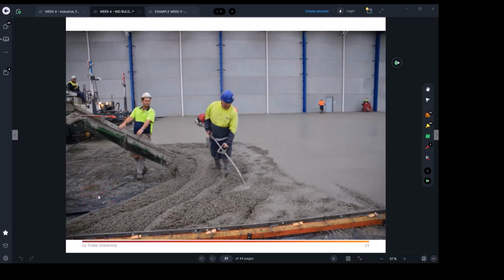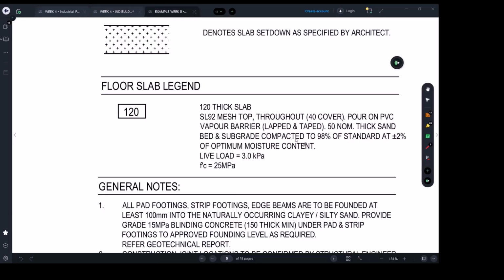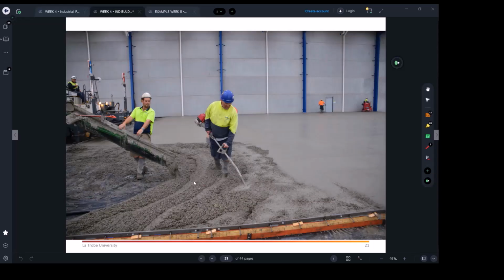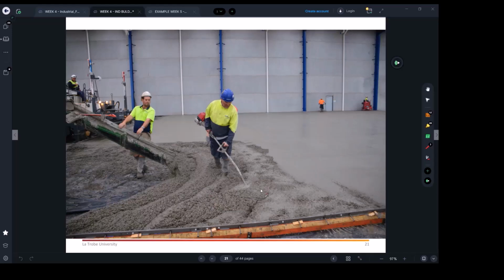Usually below the black sheet, you have the prepared subgrade. And yes, it needs to be checked as per the tables and specification we discussed. That's one thing. And then the subgrade needs to be compacted to these limitations, which would have its own contractors to do, and you're going to be given a certificate that this is done. Then it's just a placement of steel and pouring the concrete. As I said, the steel can be fiber steel, which is more expensive, or steel bars.